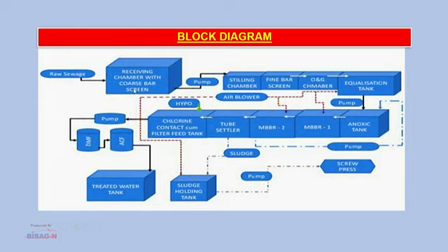Then comes stage 2, the collection sump. The receiving chamber itself is the collection sump. The sewage will be collected in the sump below ground and will facilitate the raw sewage transfer pump. Stage 3 is the pumping of the sewage from the receiving chamber to the stilling chamber. To transfer the sewage from the collection sump to the equalization tank, raw sewage submersible pumps are to be provided to meet the peak flow condition.